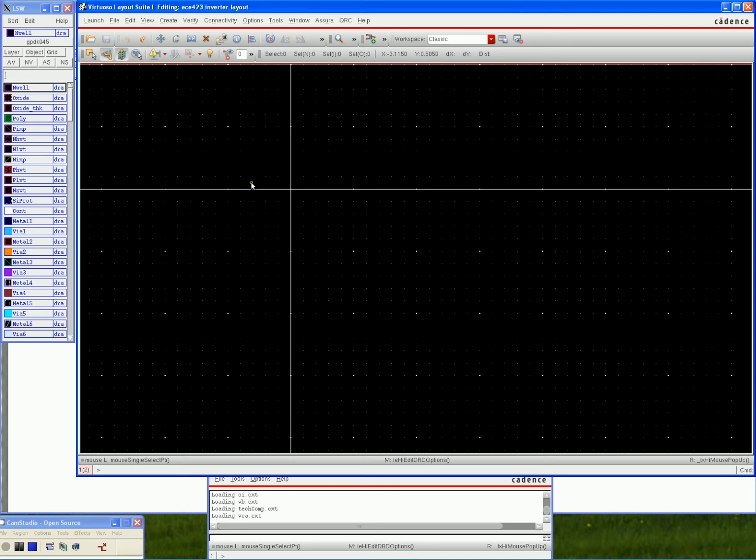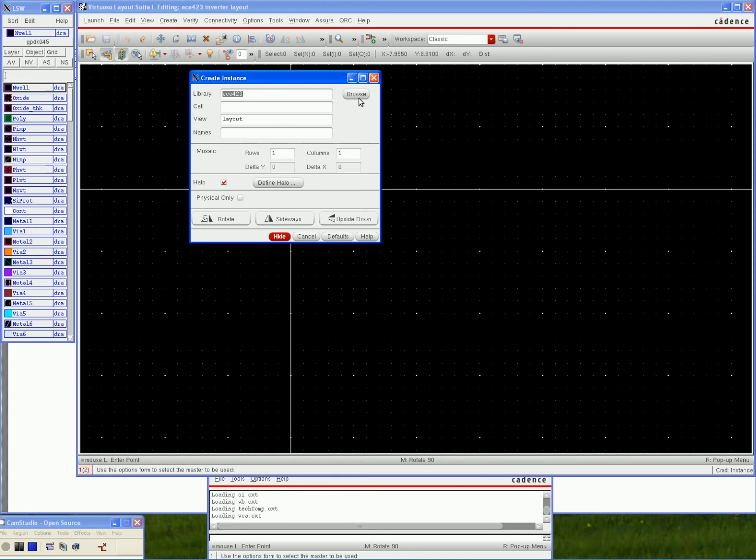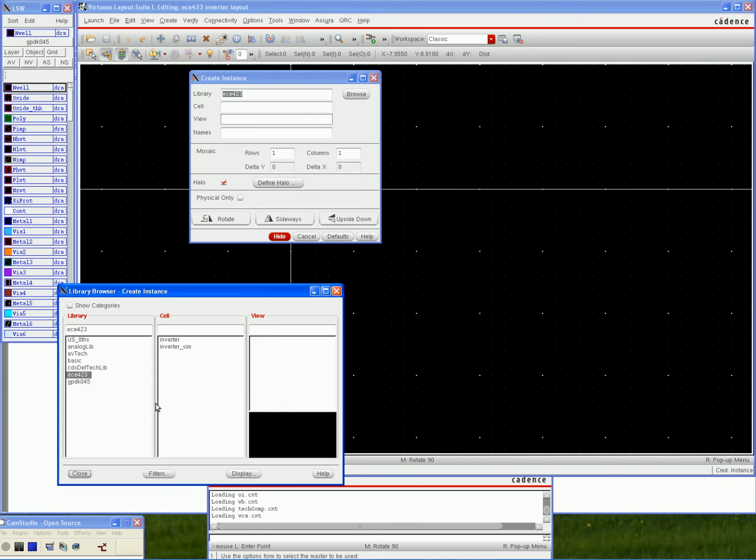And let's go to Options, DRD Edit, and we'll turn interactive mode to notify, and violation edges we'll check. And press OK. This will give us a little visual indicator later on, whenever we're moving things around, about the spacing that is required between different objects and the sizing of the individual objects themselves. So now that we have all of our options set up, we can start creating our layout.